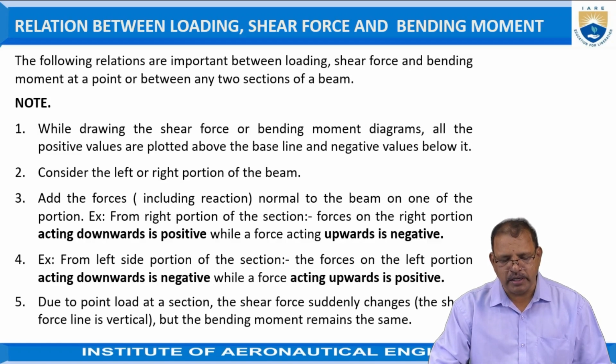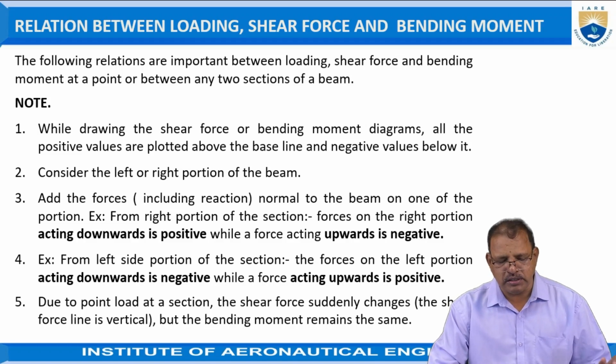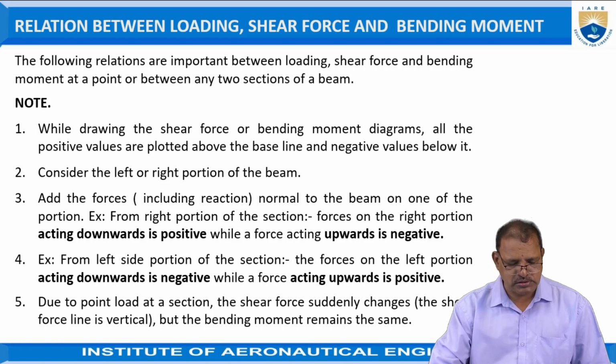For example, from the right portion of the section, the forces on the right portion acting downwards are positive, while the forces acting upwards are treated as negative. For example, from the left portion of the section, the forces on the left portion acting downwards are negative, while the forces acting upwards are positive.